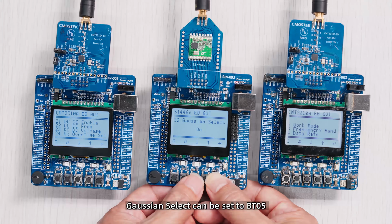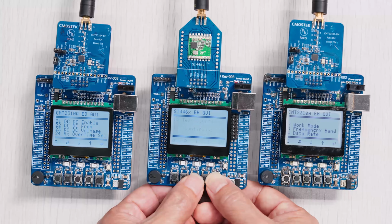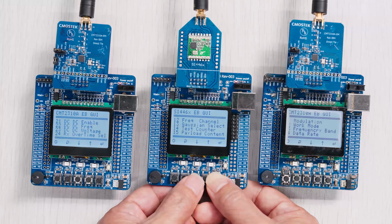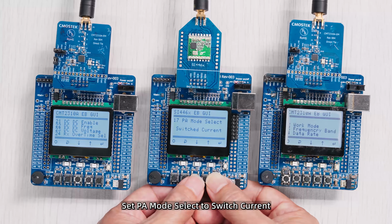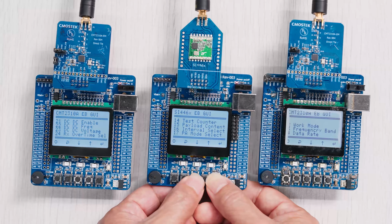Gaussian select can be set to BT05, not critical for the receiver side. Test counter to continuous. The receiver will keep listening continuously. Set payload content to random sequence. Interval select can be set to 010 or 000. Not really needed on the receiver side. Set PA mode select to switched current. Set PA-ADJ select to high power fine.